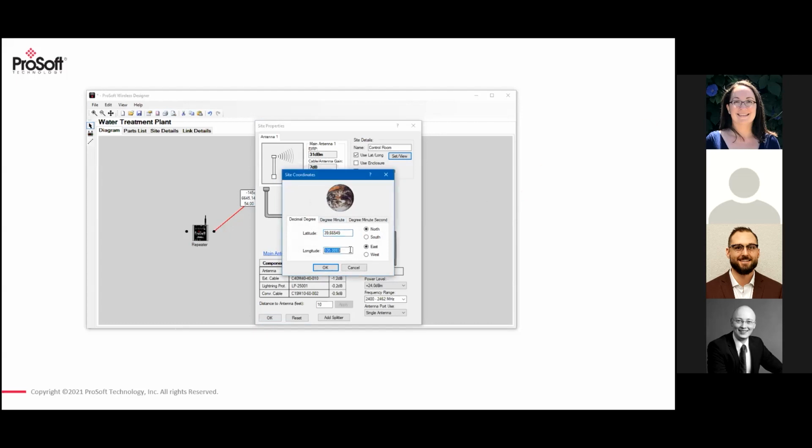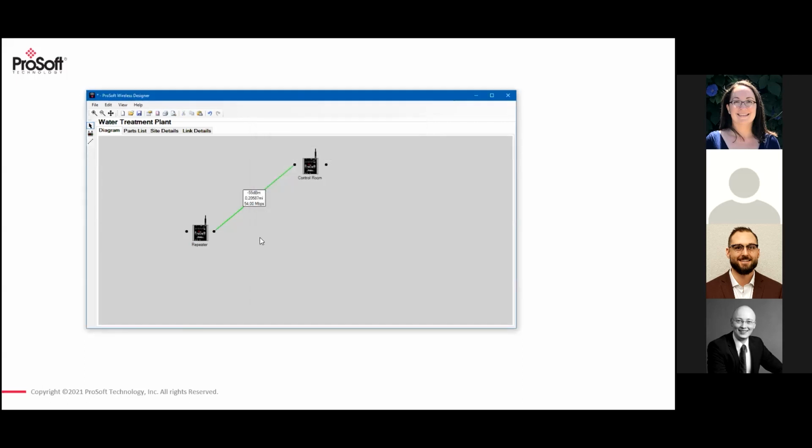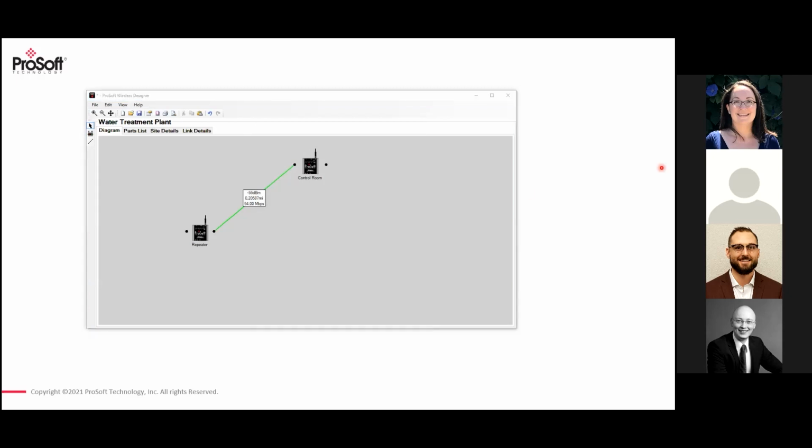So the first question was, should a spare lightning protector be sold with every project? Because it sounds like a consumable fuse. And the answer is that SPDs in general are consumable, but are engineered to handle several events. So in the typical application, one for the lifetime is no problem.